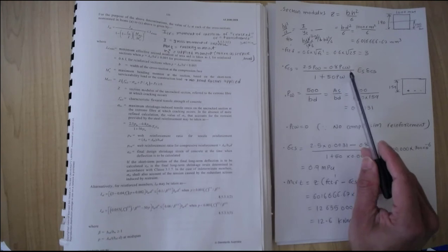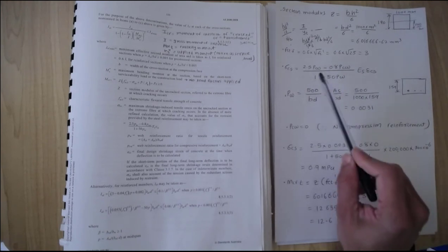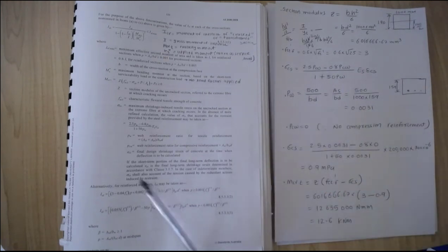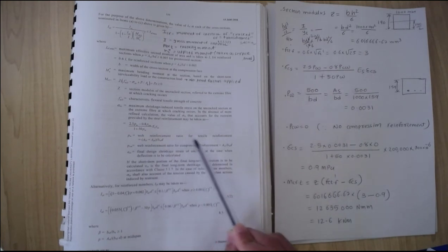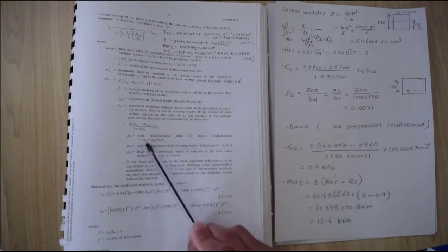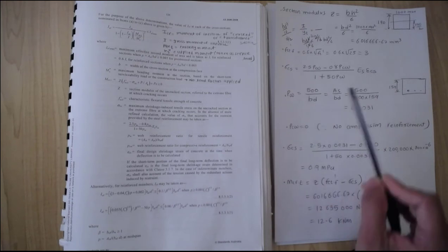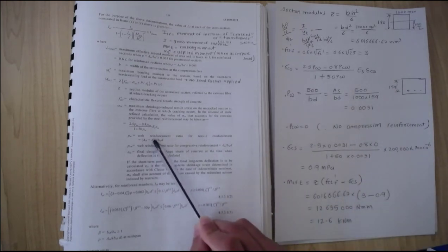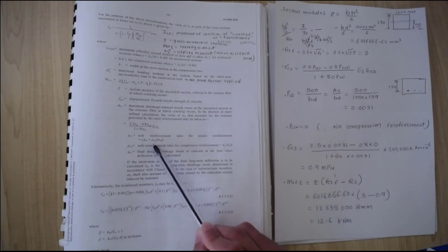Now in that one we need to look for a couple of parameters. pw is given here, which is the web tensile reinforcement ratio, Ast over bd. Now this has no prestress, so we are taking Apt equal to 0, the cross section area of tendon. Please check my beam deflection videos, where we discuss the detail about this Apt.